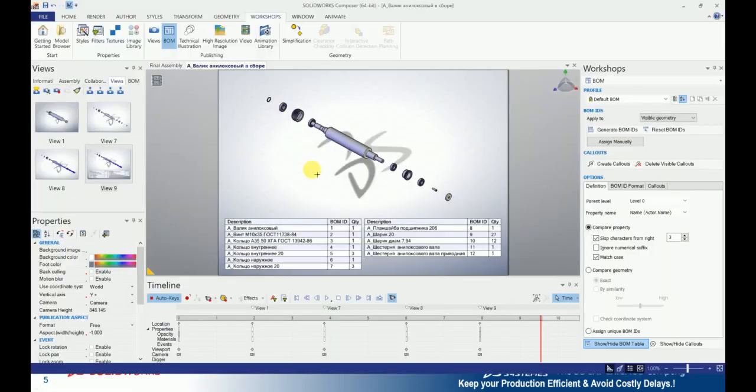So you can find that the next thing I just want to do is understand the internal components. By using the powerful tool called Digger tools, I am able to focus where I want to focus internally. Here you can find the different kinds of tool sets. Here I just want to focus on the bearing. By using the onion skin, there are different sets of tools. Here you can see the difference.